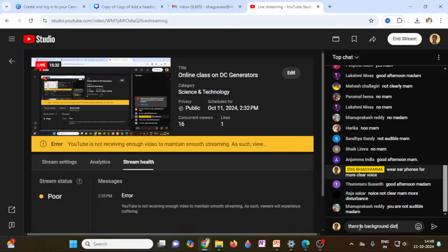So whenever the number of magnetic lines of force or magnetic flux lines linking with the conductor or a coil change, then voltage is induced in the conductor, or if there are coils, then the voltage will be induced in the coil. The change of flux associated with the conductor can exist only when there is a relative motion between the conductor and the flux.